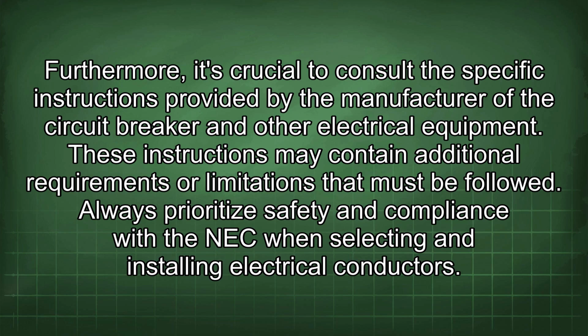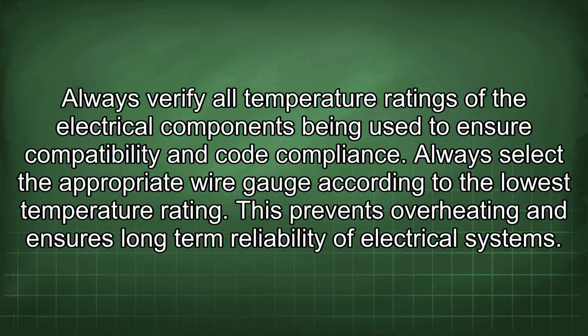Always prioritize safety and compliance with the NEC when selecting and installing electrical conductors. Always verify all temperature ratings of the electrical components being used to ensure compatibility and code compliance. Always select the appropriate wire gauge according to the lowest temperature rating. This prevents overheating and ensures long-term reliability of electrical systems.